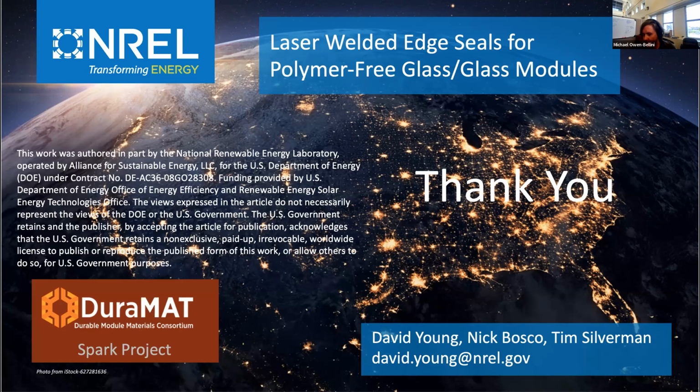I have a second question here from Denise Roberts, who's asking about the stress test. She's asking if you pull on both pieces of the bonded metal or just one piece, and do you learn the same thing if you pull on one side versus both? Nick, do you want to answer that? Yeah, sure. I'm not sure I understand the question. Typically in a load frame, you fix one side and the other side is attached to an actuator that pulls on it, but there's equal force on both sides. Otherwise, you couldn't pull on it. So you always pull on both sides. If you only pulled on one side, then you couldn't produce any stress.